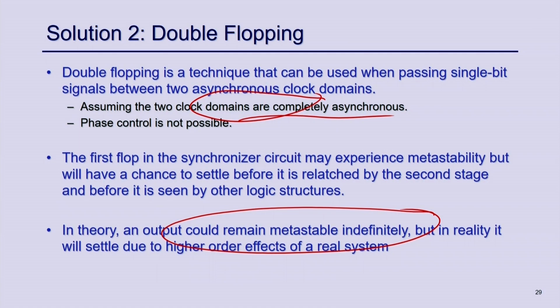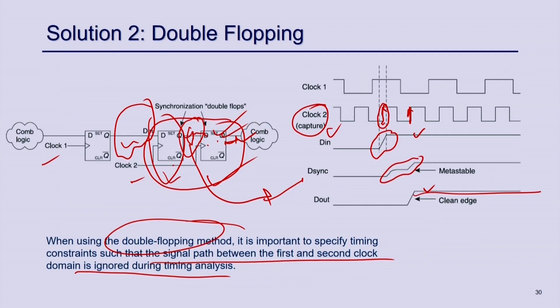As a summary, clock domain crossing is a serious issue and creates metastability in your design, and whenever you have a clock domain crossing, you have to use one of these 3 techniques. The first technique was phase control. If the clocks are multiples of each other, you should use the PLL or DLL of your FPGA to avoid that, or in general you should use double flopping for the destination clock, so that you can avoid the metastability propagating to the output.